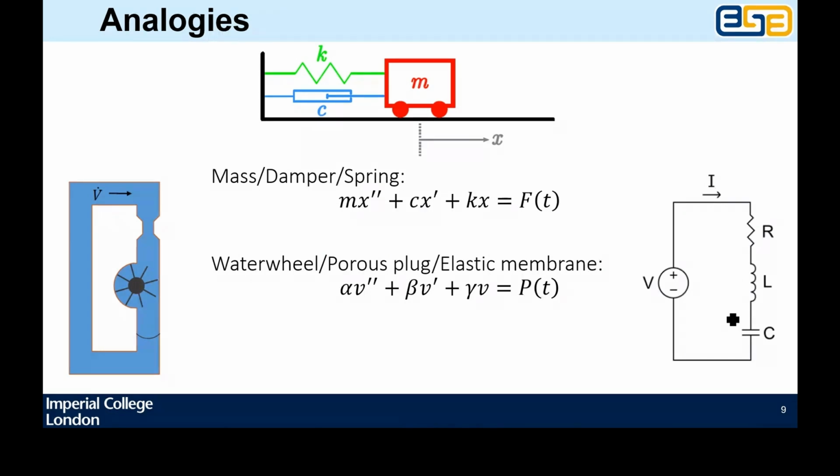A capacitor is very much like a spring, and I think people have that vision in their head already. A capacitor pushes you back. So this means that the inductor must be the kind of momentum term of this system. The inductance wants to keep going in the same way it was already going. Okay? So the L is going to be in front of the second derivative. So that's like the acceleration of displaced charge. And the C is going to be in front of the displaced charge. However, there's a small difference. So we've got it all right except for this one here, which is not C, it's 1 over C.